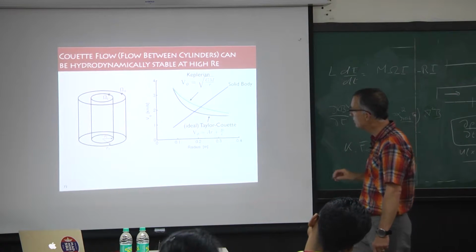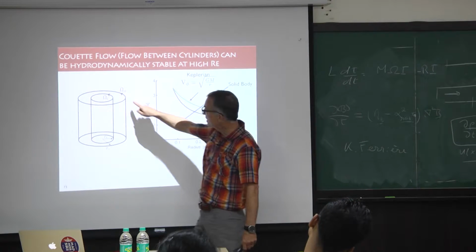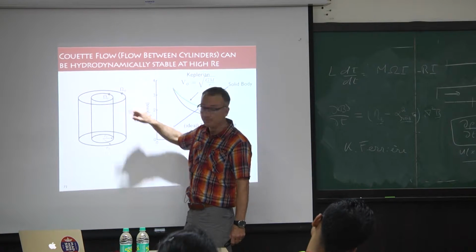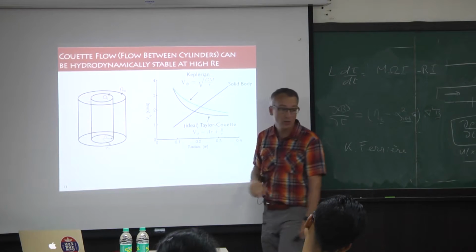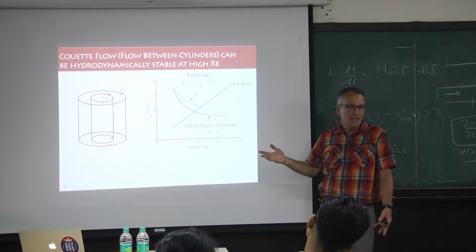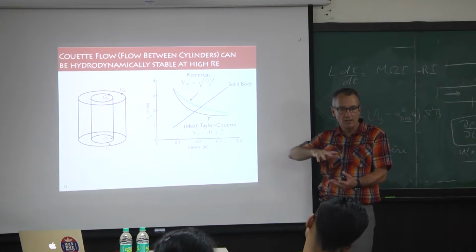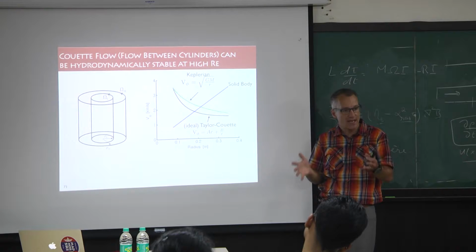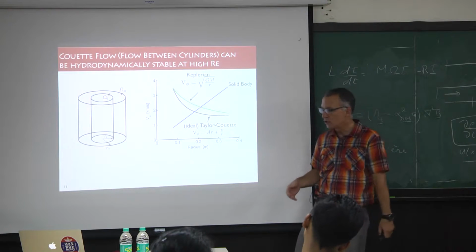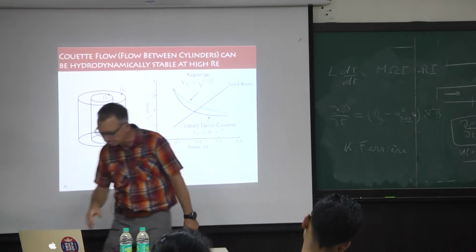I can also do something very simple, like just spin the outside. And if I just spin the outside, I would get a flow that looks like this. This is essentially a viscometer. The profiles which get set up can be used to measure things like viscosity. It's a classic fluid experiment, and it's maybe the simplest possible 2D-like experiment. Okay?